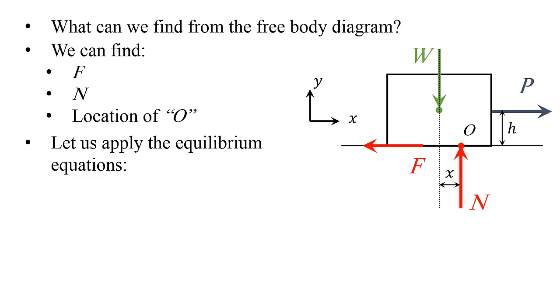To apply the equilibrium, I need to define my coordinate system, and I need to define the distance x, which is the distance between point O and the line of action of W, and I need to define h, which is the height where the P is applied. Now I'm ready to take the summation of the forces and the summation of the moments.